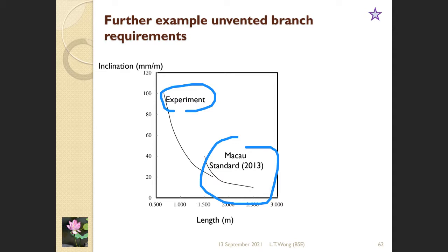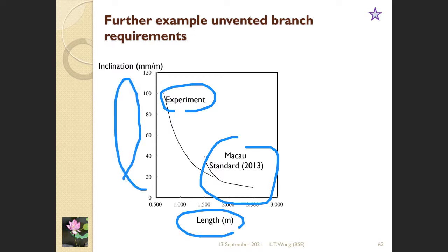I think in your laboratory there's a quite old-fashioned experimental test rig, to pump in the water and test the siphonage action and how much water seal we retain after the discharge. Right now, in this presentation, I shall draw here the length of the branch pipe, and the branch pipe arranged with the inclination, which is a gradient. Different gradient and different length will have different effects on the siphonage.